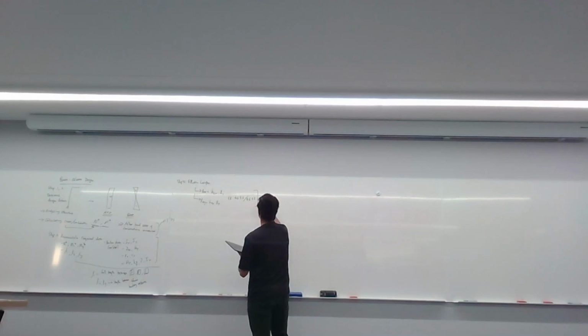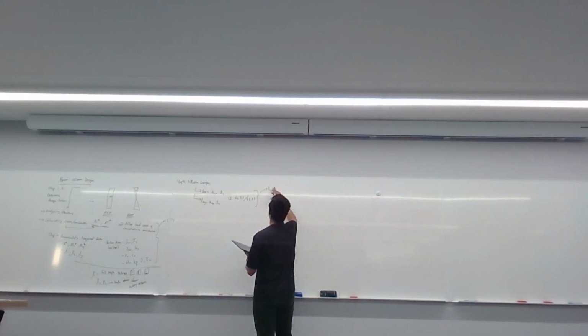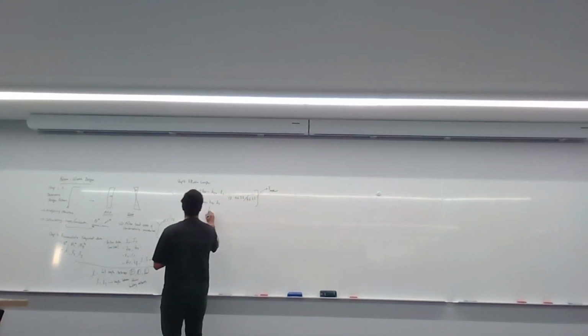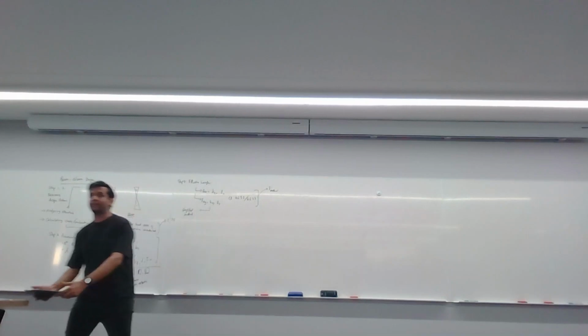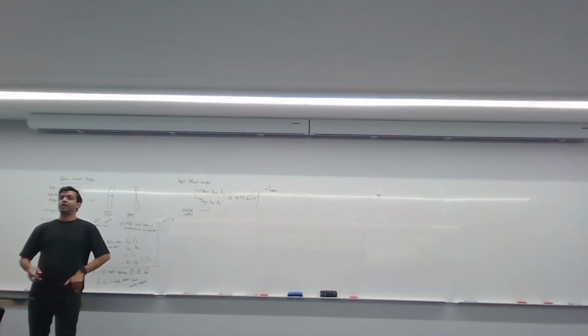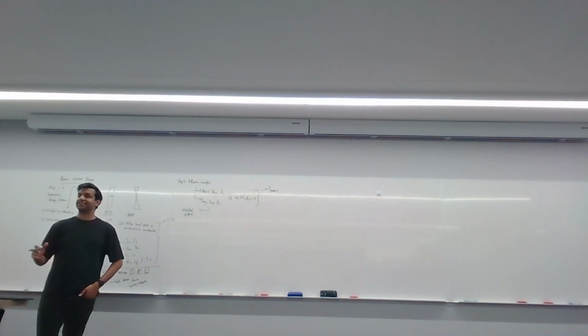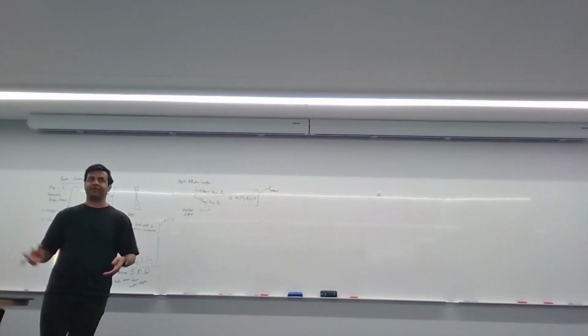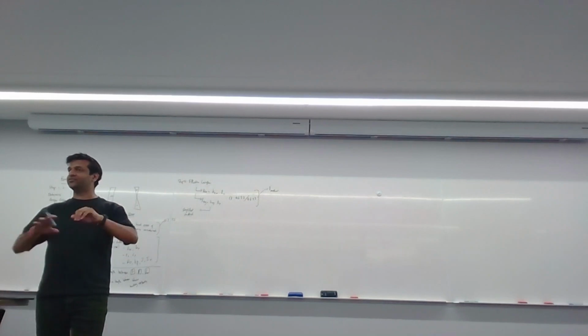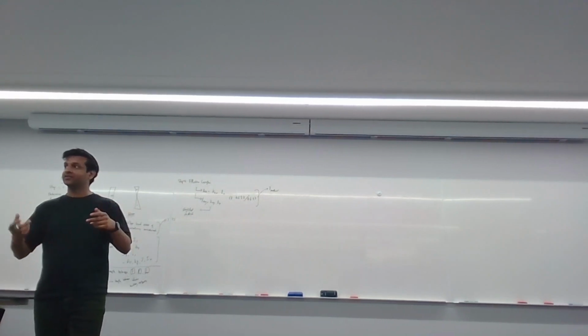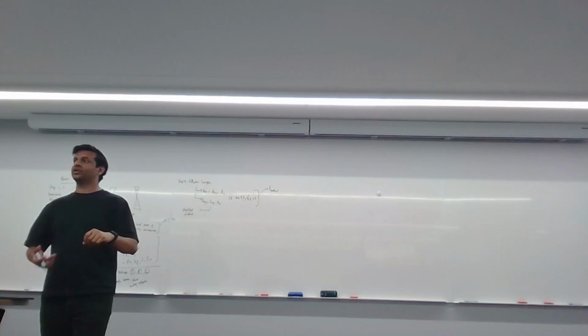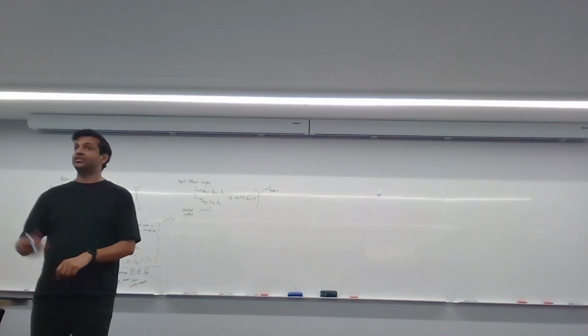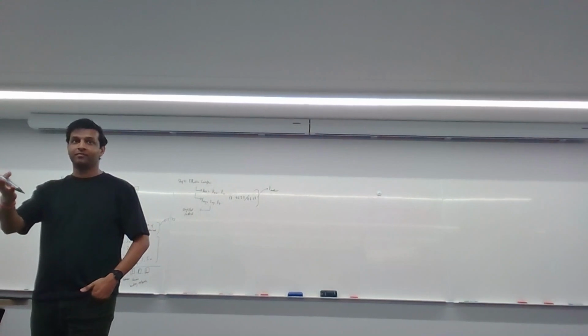Now that was the gamma method. There is also the simplified method, or rather the idealized method. So remember, how do you do an idealized method? Generally that's in the case where the question doesn't give you the entire frame. It just shows you one column, and it tells you, simply put, the column is pin, pin. Pin on the bottom, pin on the top. So in a pin, pin case, is your effective length equal to the total length of the column?